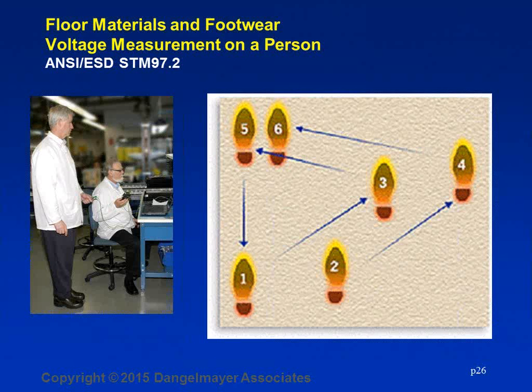Ginger, we have a good question on this topic. Should a wrist strap be off when doing this walking voltage test? Yes. Clearly it has to be off so that you can monitor body voltage. Right, because your body voltage will stay at ground with a wrist strap. This is a very good way to test if a wrist strap is not working properly.